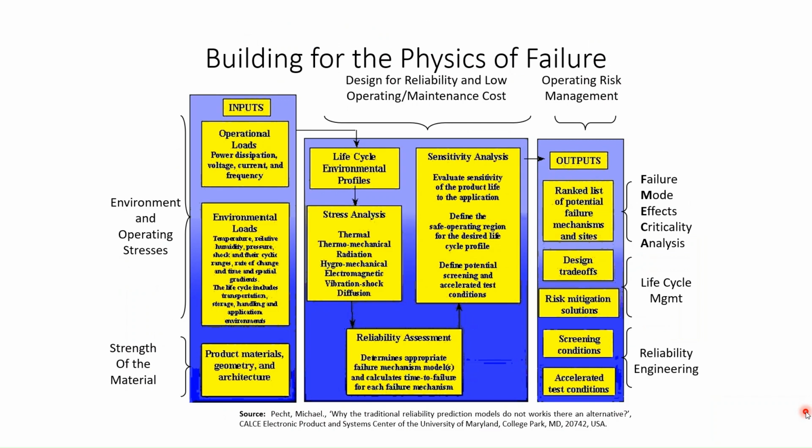The mechanisms of failure caused by stressing components has become known as the physics of failure, POF. The chart shows the best practice process now adopted in designing equipment following recognition of the influences and effects of POF. The parts are modeled by finite element analysis or other test regimes, and their behaviors analyzed under varying operating conditions. The probabilistic life cycle performance is identified under the various situations, and the results indicate the design limitations and operating constraints to achieve a desired failure-free life.